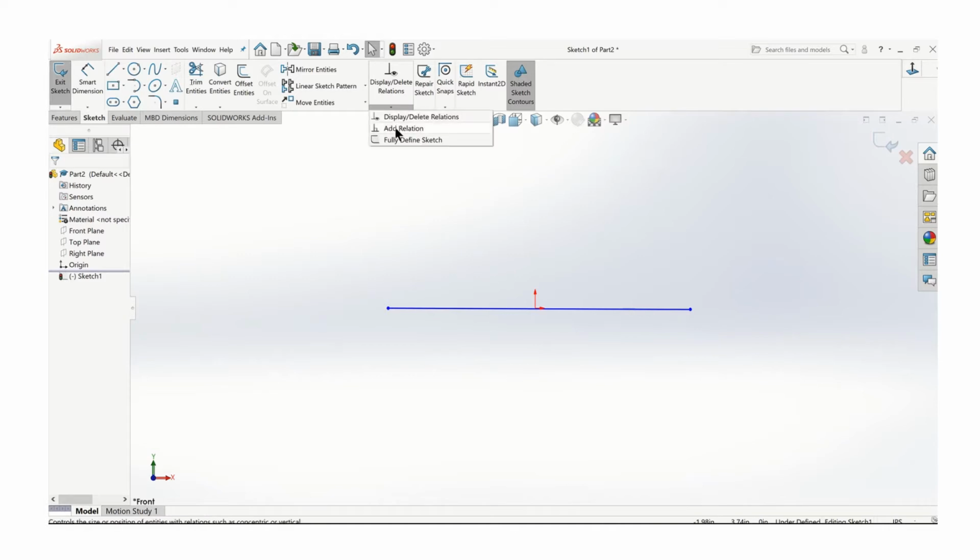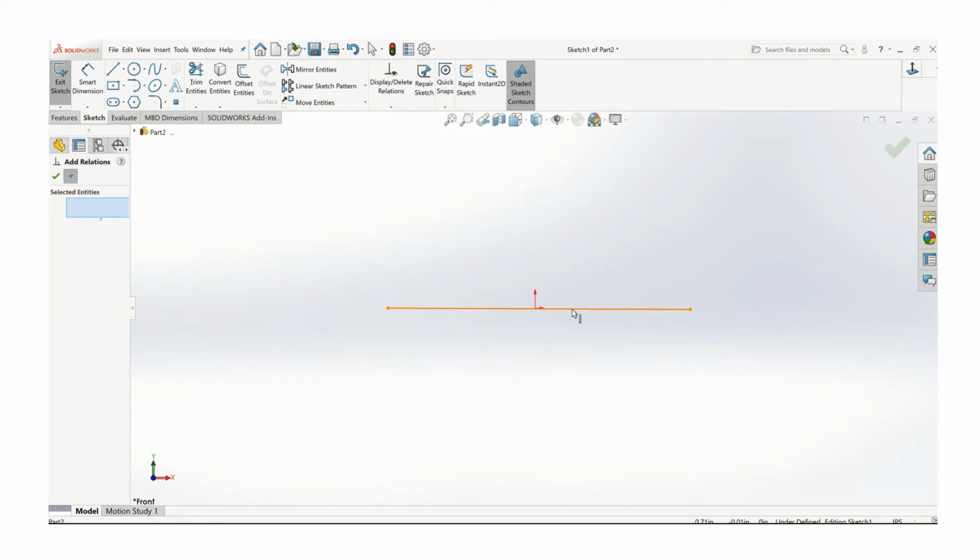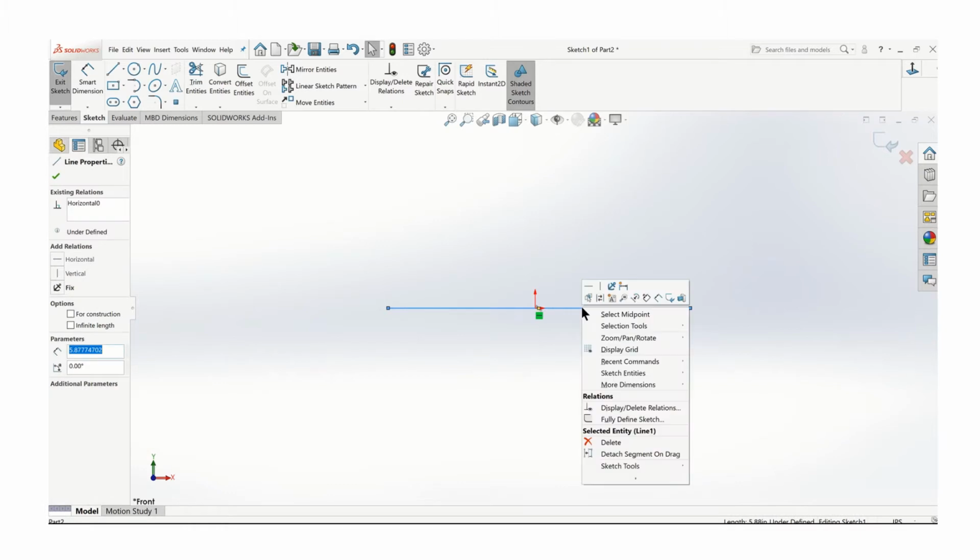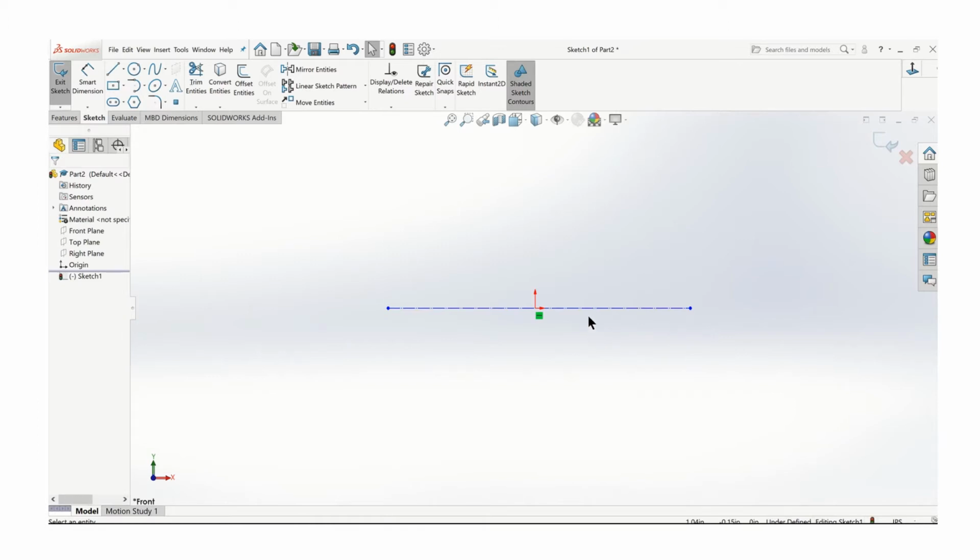Oops, I have to make sure that's a horizontal line. Okay. Now if you right click on that line, come up here and you see that icon, that's construction geometry. So I'll turn that into a construction line. A construction line will be only visible in terms of use for construction. When you leave your sketch, that line kind of goes away.